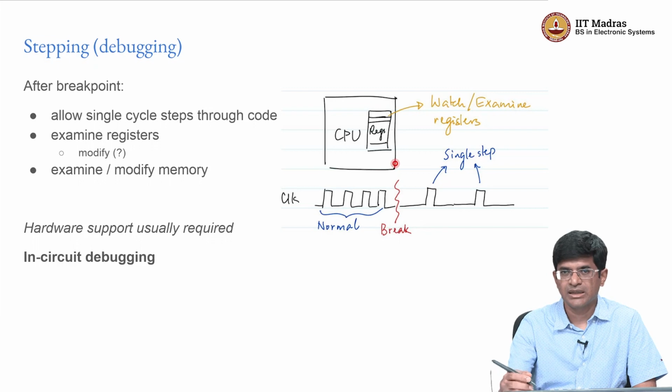What you do is you have some other way by which you can control how individual instructions will be executed from that point on, right. But in hardware, you could actually get to the point where you break the clock, you stop it from toggling, and then you can control the clock from an external mechanism and say, okay, I will single step it, I will allow it to go through one up-down variation, which is one cycle, and I can space those cycles at whatever point I want.